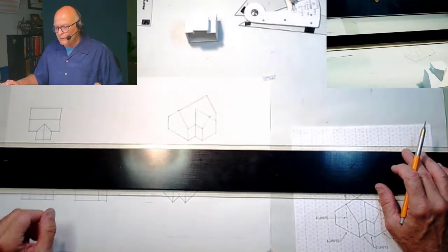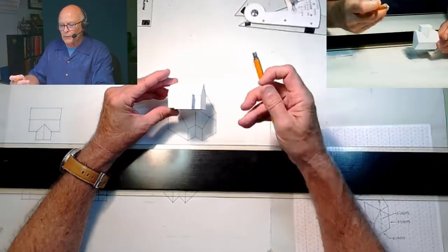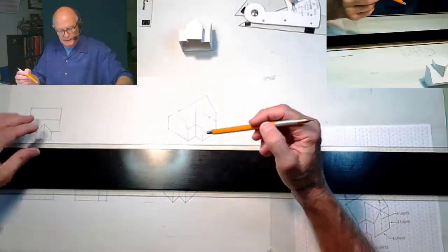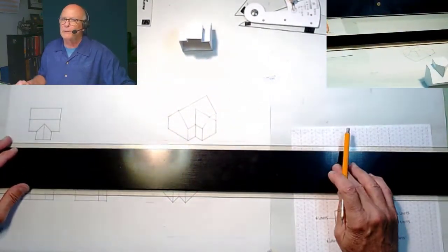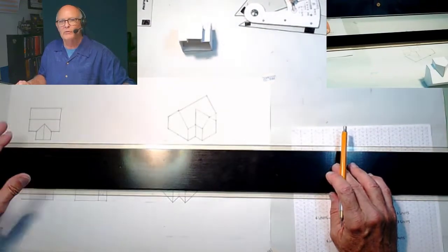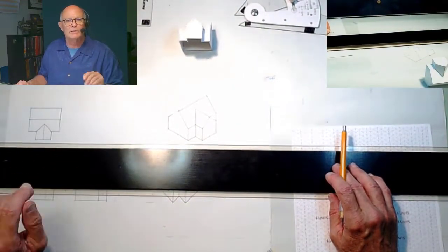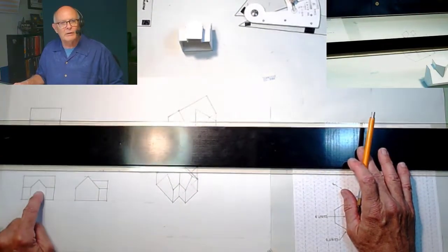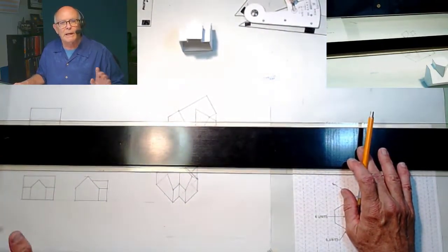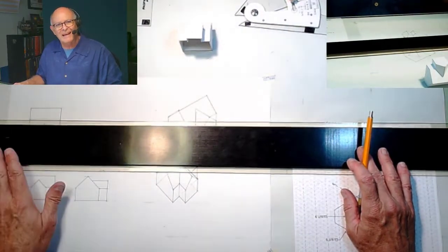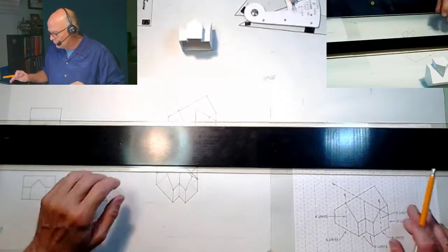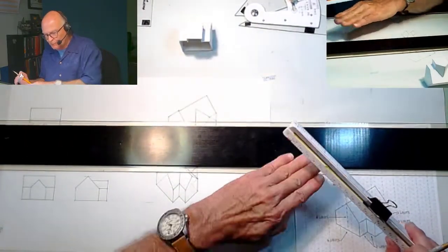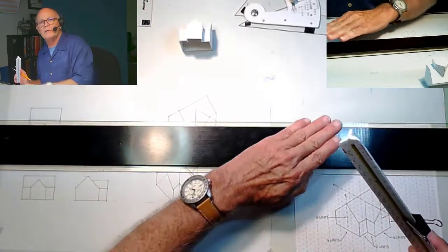As we do this, we're going to orient ourselves. We're going to draw this elevation. We're going to replicate it, but be light with it, okay? Because not every line is going to stay. Some lines are going to have to be erased and projected in a different way soon after. This elevation right here is something we can replicate right off the bat, but draw it light. Again, we're going to be erasing some of these lines. Okay, having done that, I'm going to come over here, knowing that my projection is going to go in this direction.